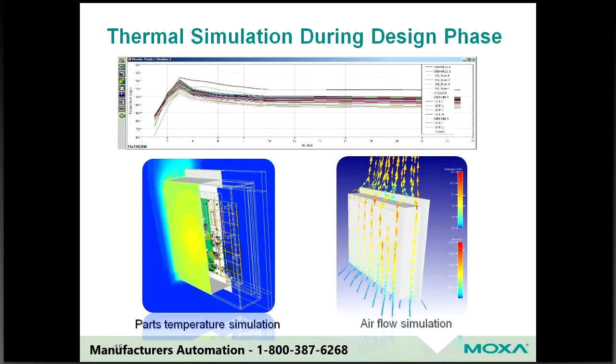You'll see some competitors claim that they're industrial grade, but the heat dissipation will be red in certain sectors of the back of the panel, which is a recipe for overheating and short lifespan of the unit. And the reason why it's so even is not only the internal construction, but those vertical fins that I mentioned earlier control airflow, and for whatever reason our testing has shown that vertical fin design is much more effective than lateral. You see the thermal temperature graph on top.